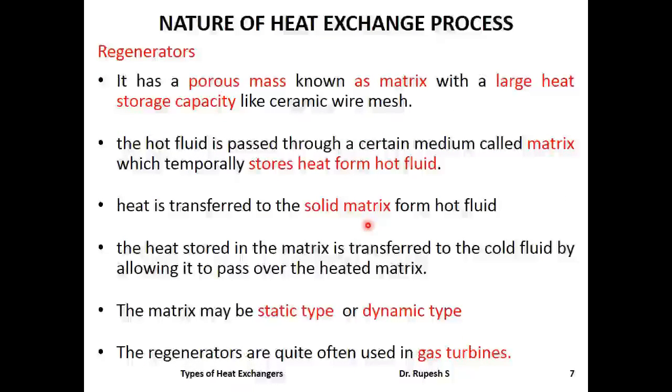Unlike recuperators, regenerators consist of a porous solid medium with large storage capacity known as matrix. This solid matrix receives and stores heat from the hot fluid which is then transferred to the cold fluid. Based on the type of matrix used, we can classify regenerators into static type and dynamic type. Regenerators are mainly used in gas turbines to recover heat from the exhaust gas.